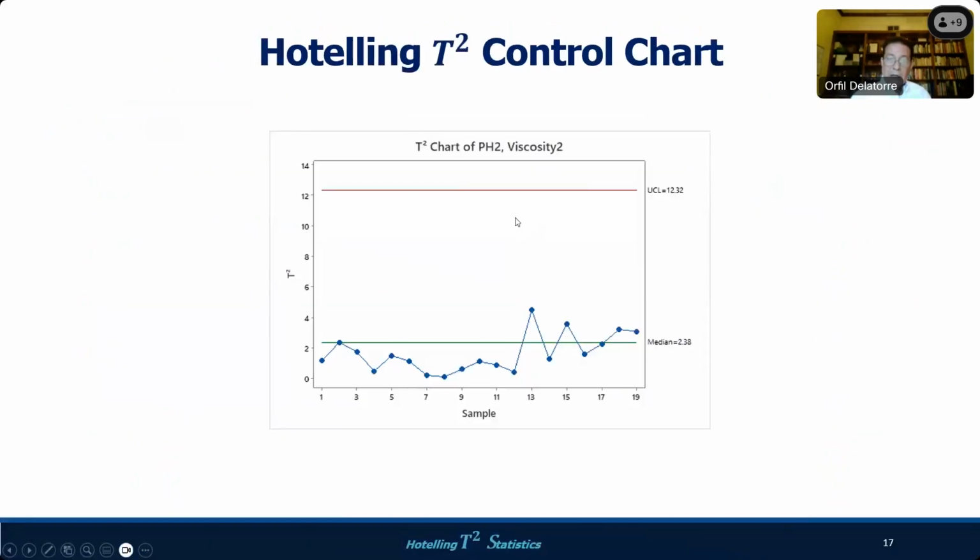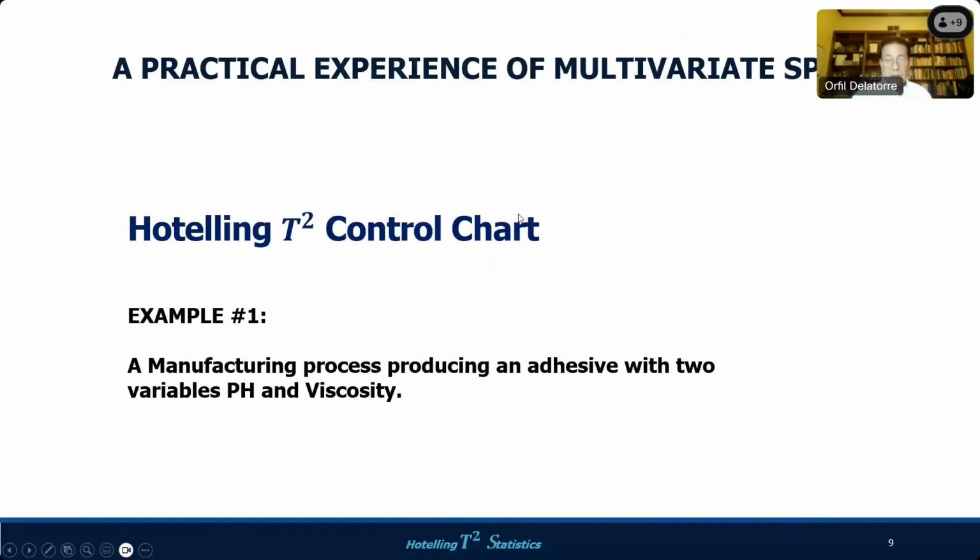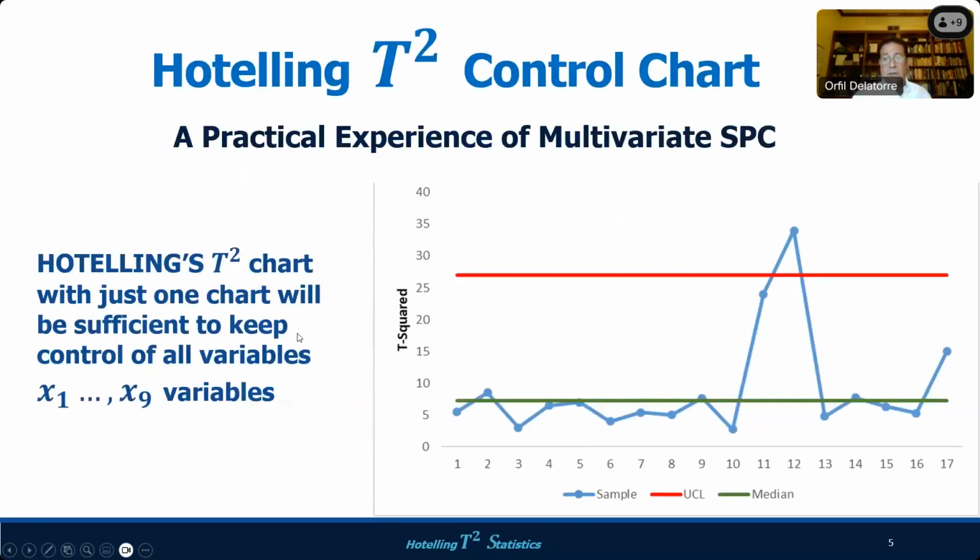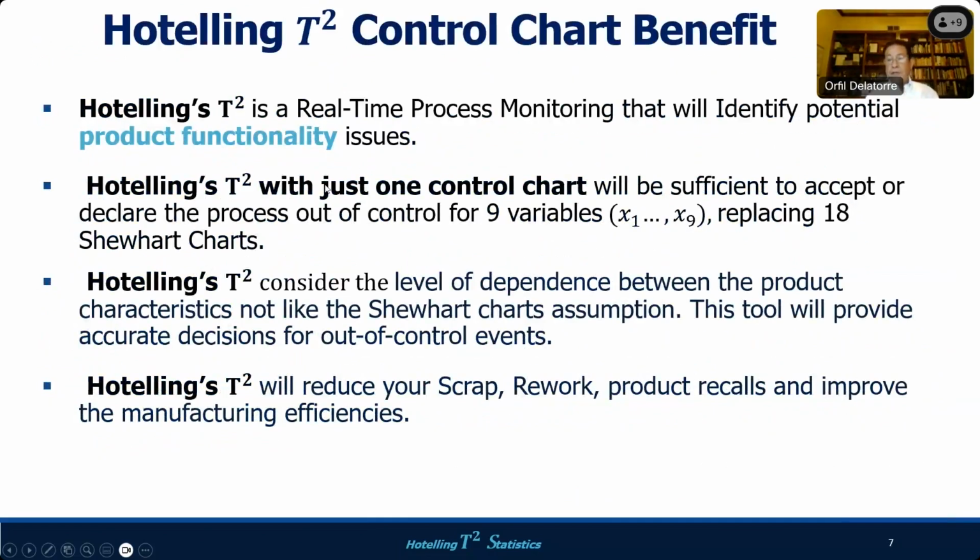I told you, I'm going back to the 9 measurements as a limit, and you can ask me why only 9. Well, the thing is that if you consider 10, 11, 12 measurements in the T-square chart, since it's a test of hypothesis to declare the process out of control or not, guess what? The type 1 error in the test of hypothesis degrades. And you're going to see, if you see Statistica, that they consider using 10 variables. I disagree with these guys because I did the calculations. Whenever you use more than 9, the type 1 error degrades. So maybe Statistica made it that way in order to make it easy. Okay, consider 10. So it's not a big issue. I don't.